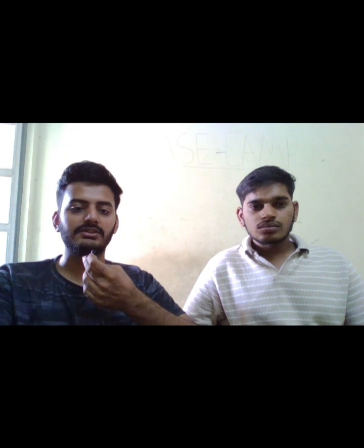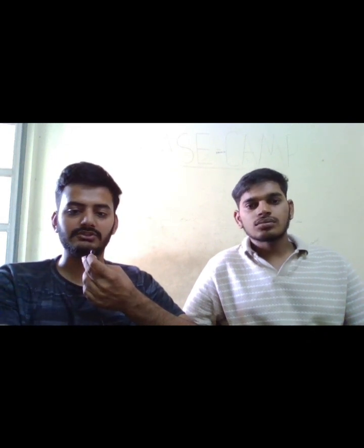Now coming on to the summary of these key equations, which we will study in our dimensional analysis. The full Navier-Stokes equation is there. For the generalized case and creeping flow, the dv by dt term will be zero. The rest will not be changed. The condition for creeping flow is Reynolds number less than 1.